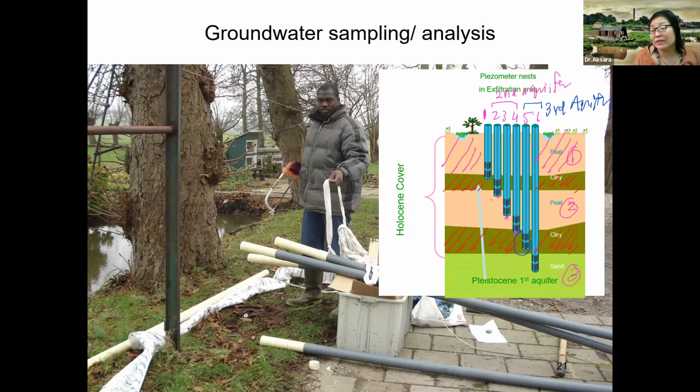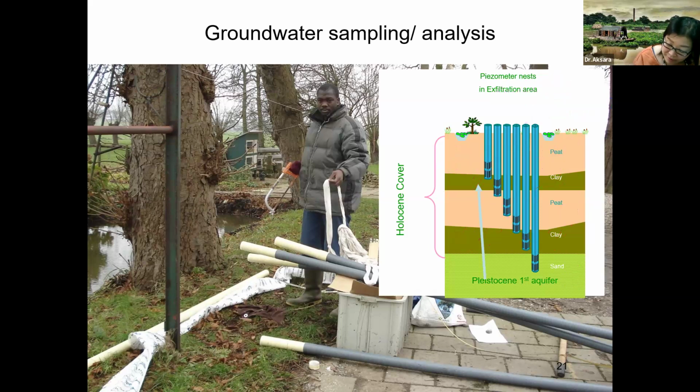The second reason why they have the opening in the clay layer is probably some uncertainty. You see that your clay doesn't really have uniform thickness. It has some thinner layers and also thicker layers. So when you install the well, sometimes your opening is not really consistent with the aquifer layer. So that's possible.